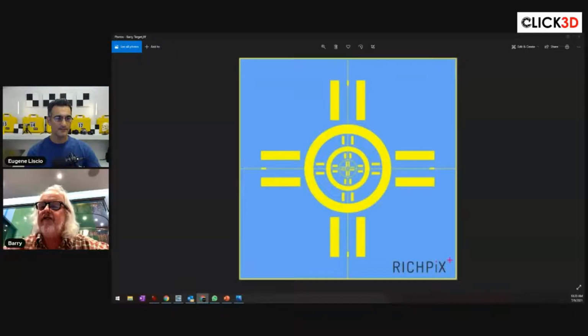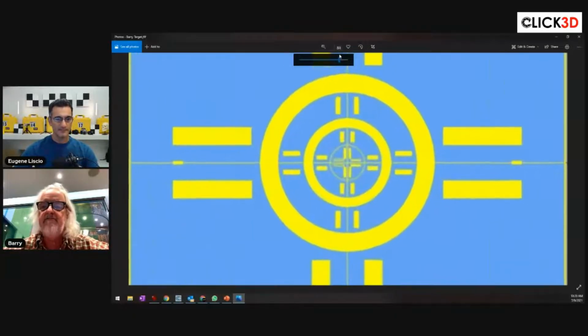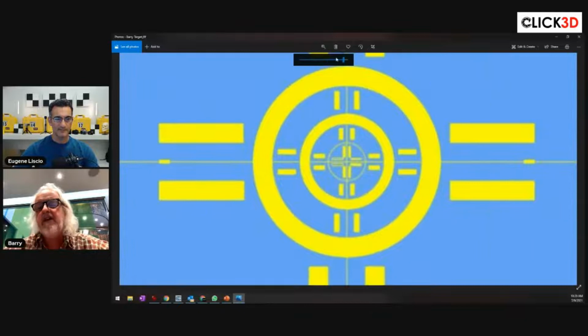It's really essential there that we get to measure the control points very accurately. So we'll be using optical instruments, total stations, to shoot the targets. Appreciate, if you're doing aerial stuff and GPS, then obviously you've got different, but we're having to get targets centering down to sub 0.1 of a millimeter.